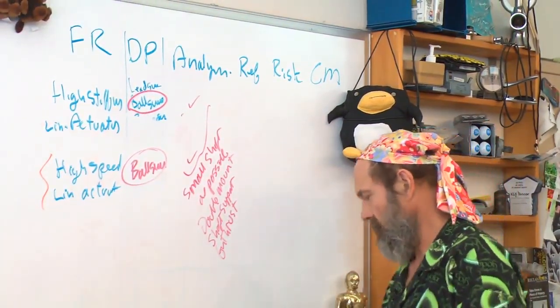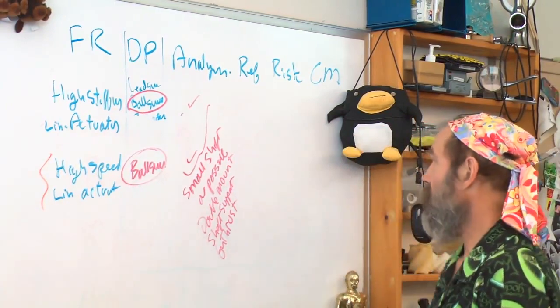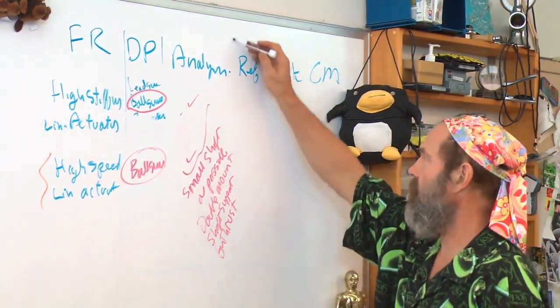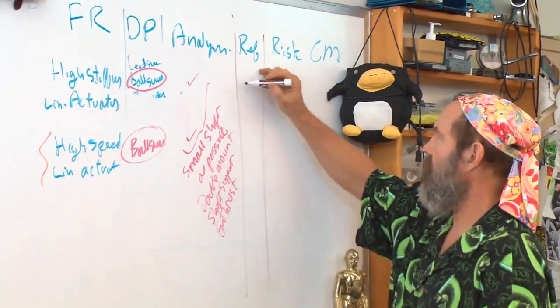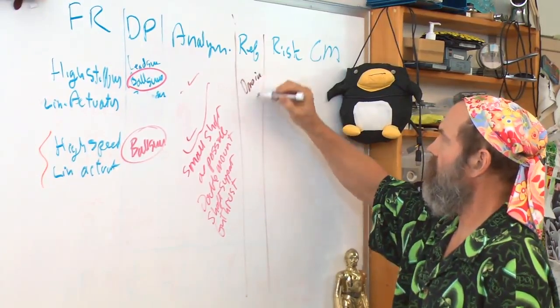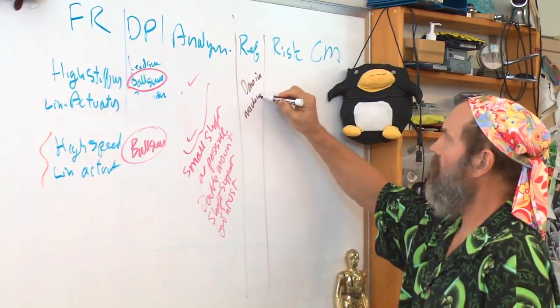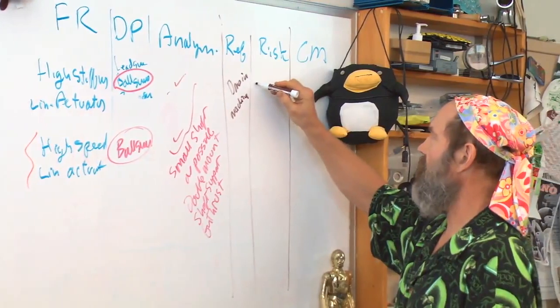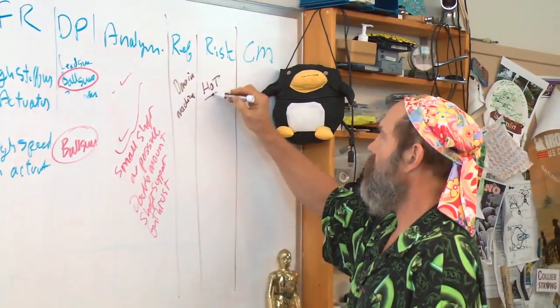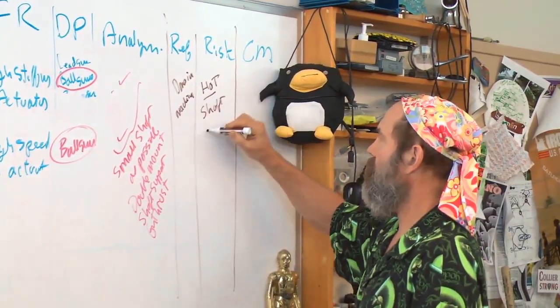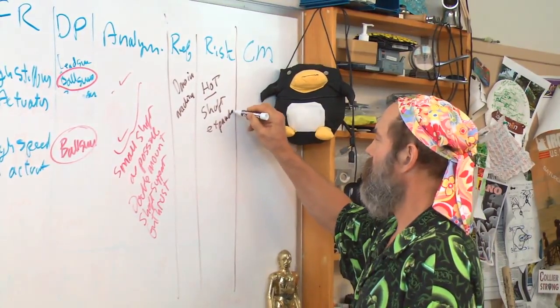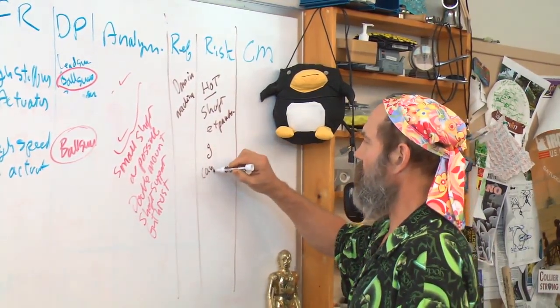Wonderful. We also happen to know that this is done quite often in machines. But the risk is, for high speed, it gets hot, shaft expands, and can buckle.